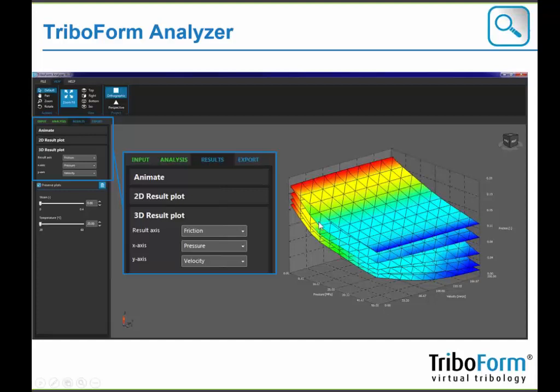So what we see here is that we have a pressure dependency, and if we increase the strain in the sheet material, at a certain moment you will also have a velocity dependency. So this is a four-dimensional friction model, and it's hard to interpret it from this figure.